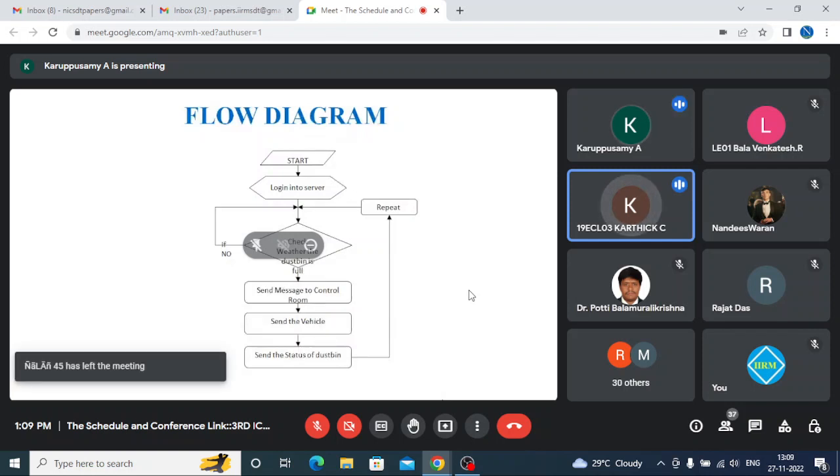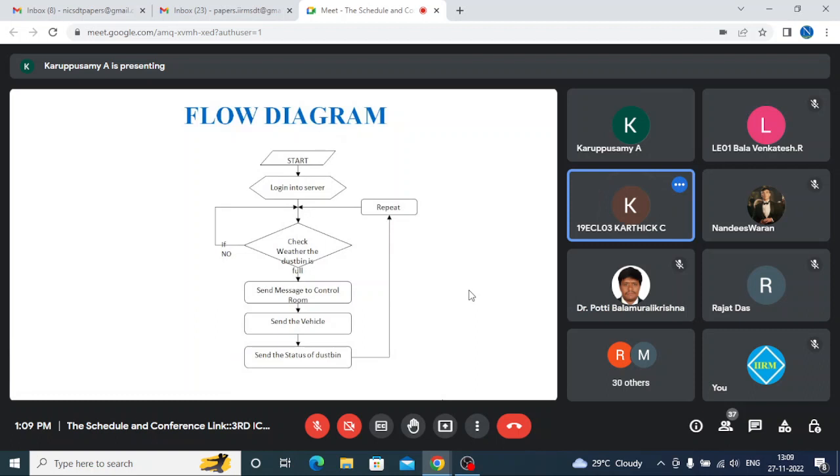The garbage monitoring system is shown step by step in the flow chart diagram. Here, at the start, the garbage bin is unfilled. The sensor placed over the bins senses the level of garbage collected in the bins. If the sensor senses no garbage in the bin, then it does not send information to the person monitoring the control room. Else, if the sensor senses garbage at a level between 0% and 70%, it specifies the level in the garbage view.